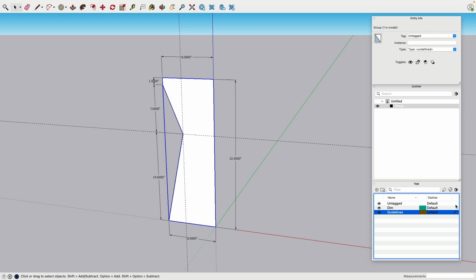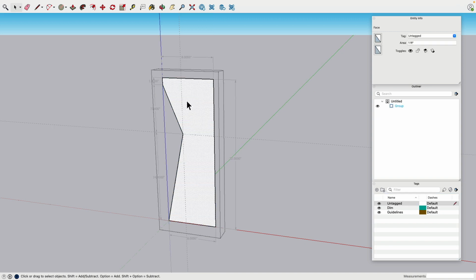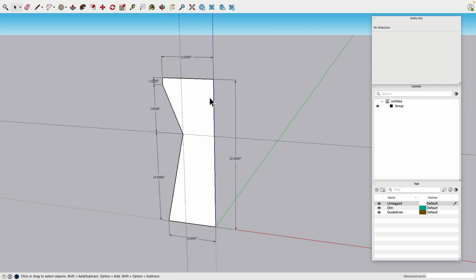I can make the edit of different tags. Don't ever touch this one. Keep this on untagged. The geometry, so the mesh, has always to be created on untagged. That's the best way. And then we make our groups and they all remain in untagged, period. We can later structure our design, interior, exterior, via groups in the outliner. Okay, very good.